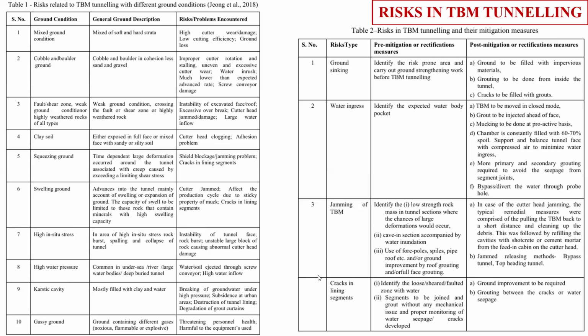Similarly, if there is high in situ stress, high water pressure, or a cavity, these types of conditions, particularly in the Himalayan regions, the TBM cannot tackle, because till date, all the TBMs manufactured around the world are not 100%, or even 70-80%, suitable for Himalayan rock conditions. In the Himalayan rock conditions, we encounter very mixed ground and groundwater conditions, frequent fault and shear zones, and sometimes squeezing ground, high in situ stress and high water pressure. The TBM cannot tackle this whole combination.